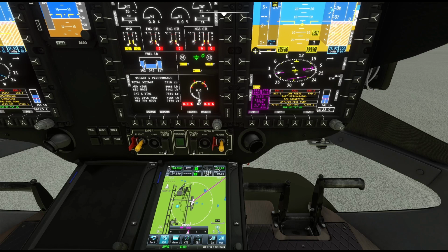All right, so this is going to point towards the actual ILS station, and this points towards the course that it pulls in. So it knows that that ILS is a 185 heading, and so it points towards the 185 and tells you you need to be flying a 185, but you need to slide right to get on course. This points directly at it. So using these two, you know you need to fly in this direction, otherwise you're never going to intercept this before you get to it.